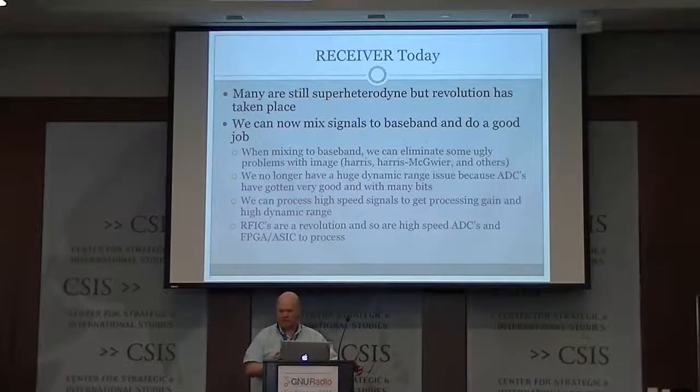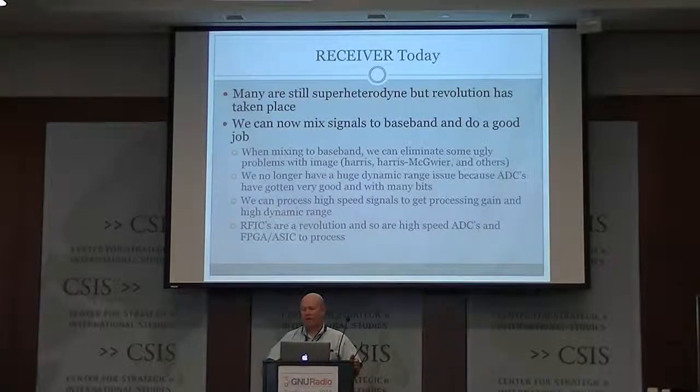And the other thing that's happened is a superheterodyne receiver system had to have cascaded stages. It had to have a couple of mixers, and things move up and down, and filters and all sorts of stuff. And every one of these stages in a superheterodyne receiver, there's no such thing as a linear analog circuit. It doesn't exist. Every single real analog circuit has nonlinearities in it. And much of what we do when we characterize the receiver's performance is measure how linear they are by measuring things like IP3 and IP2.